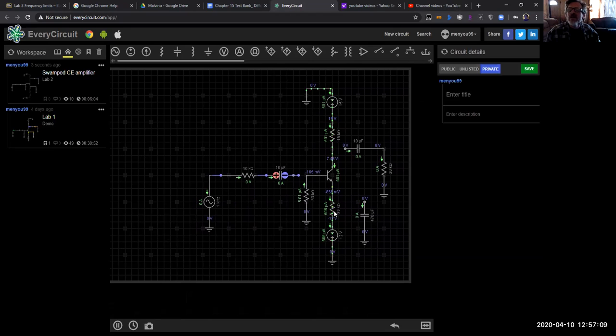And we've seen, if you remember before, when the emitter was just tied to ground, how unstable of a circuit that was. And so by putting a negative supply with the resistor as a way to effectively control the transistor, there's still beta dependency with this, and if you've seen, even when I added this in here, right?